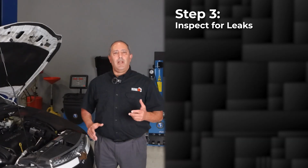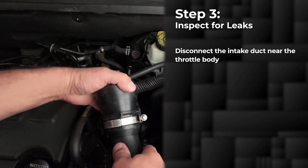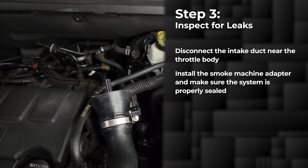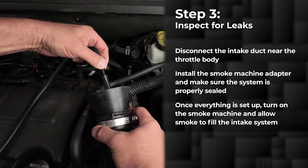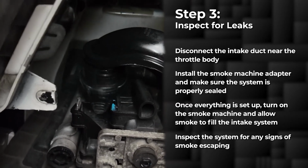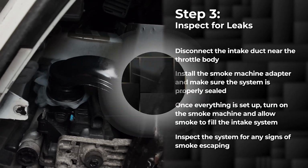To check for possible vacuum leaks, we'll use a smoke machine. First, disconnect the intake duct near the throttle body. Next, install the smoke machine adapter and make sure the system is properly sealed. Once everything is set up, turn on the smoke machine and allow smoke to fill the intake system. Then, inspect the system for any signs of smoke escaping. Here we found that the intercooler is leaking. You can see smoke from there.